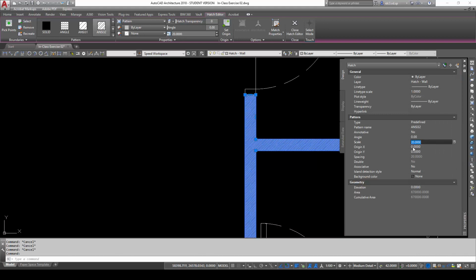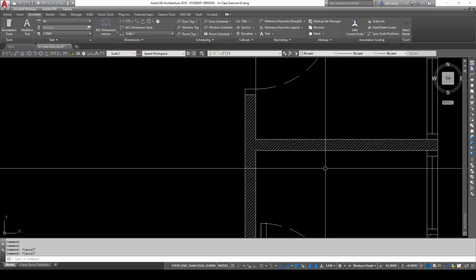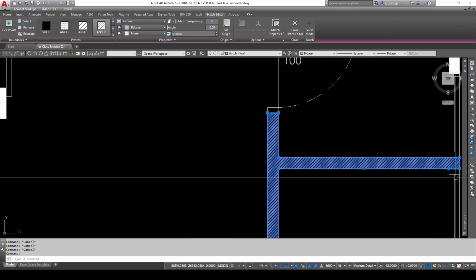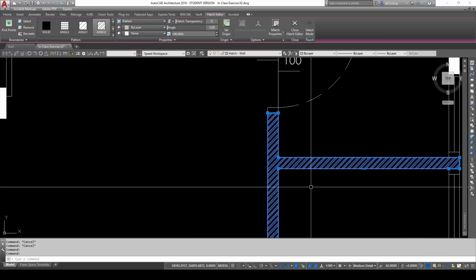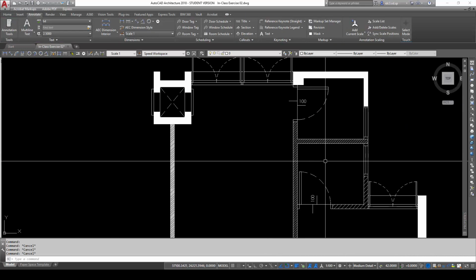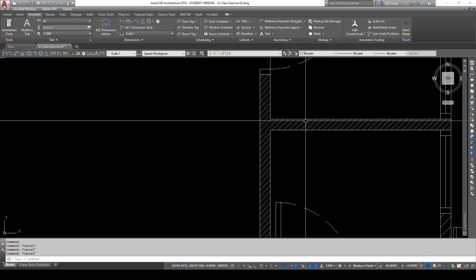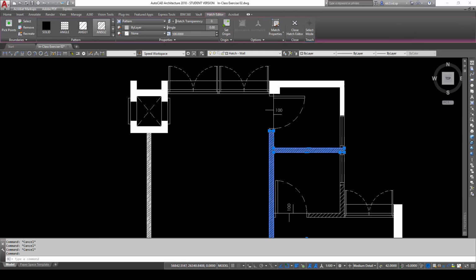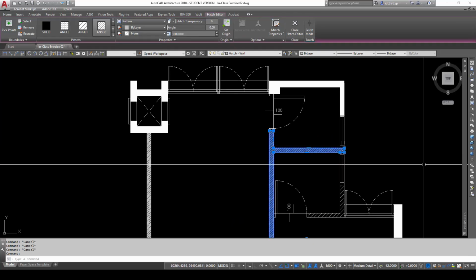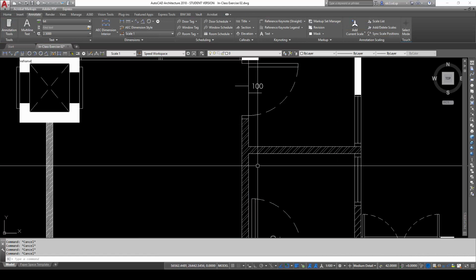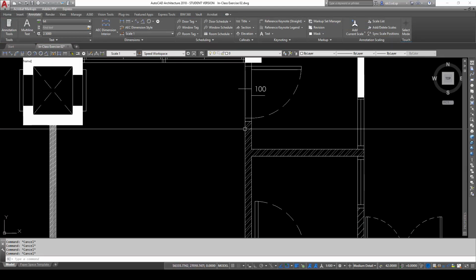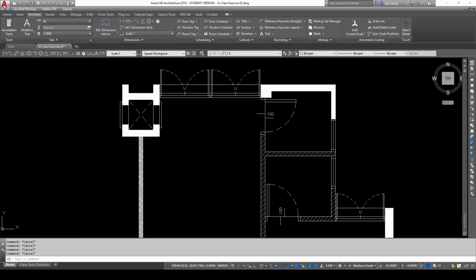At the moment, this was referenced at 20 scale. So I'm going to try to change this into 50 scale to see if that will make more sense or not. Or if not, maybe make it a little bit more with a 100 scale, for example, and see if the effects will be better or not. All right, this one really depends on the person drawing it here. There's no defined standards on the scale of it. So perhaps I'll try 200 to see if that will work better. Yeah, I think 200 seems to make this wall hatch pattern more defined.